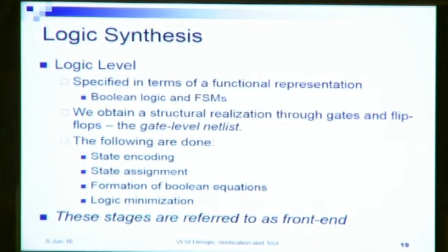This RTL description as well as this FSM has to be encoded in terms of Boolean equations, and for the FSM we also have to do a state encoding, assignment, and realize it in terms of a digital circuit.